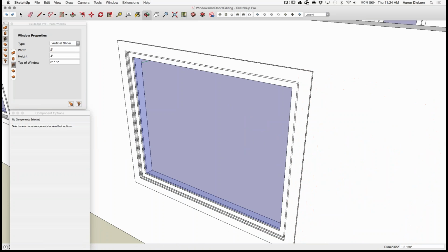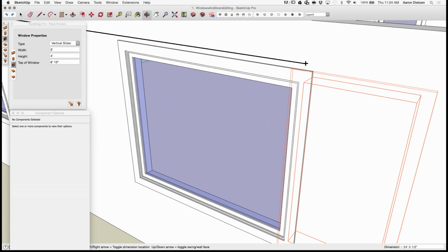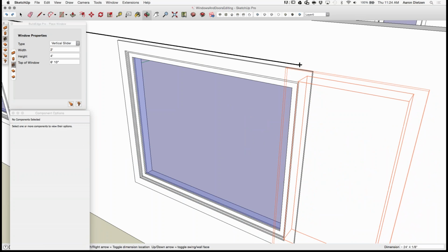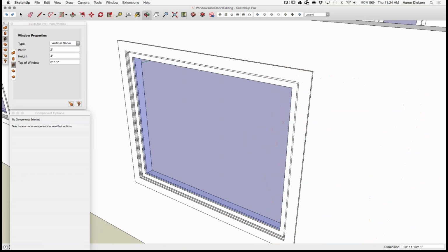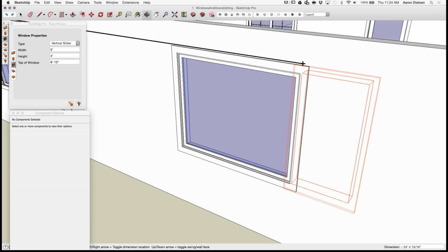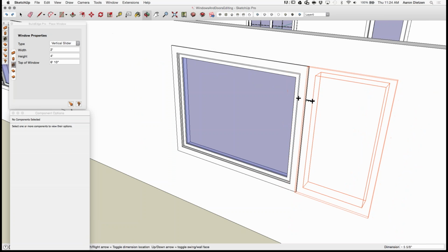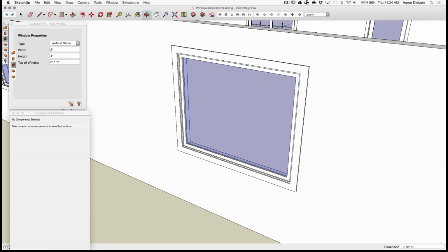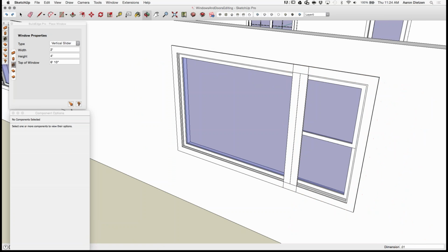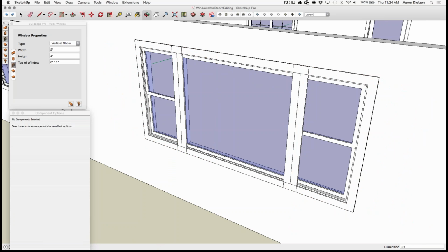This is where I have to kind of fake this a little bit, because I cannot actually get these two to butt perfectly. They can come real close, but if the 2 openings overlap, it causes problems. So what I'm going to do is come like this, and at the lower right corner, I'm going to put a dimension in of 0.01. That's going to place my window overlapping slightly. I'll place this other one in here, 0.01, and those 2 will go in and overlap.